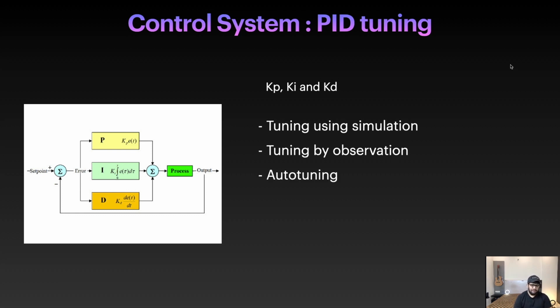One thing that was also very common a couple of years back, when new people were coming into this hobby and they were not from a technical background, they did not understand KP, KI and KD and PID tuning. So some firmware has a feature called auto tuning. What auto tuning is, you take off your drone, you bring it to a certain height, and then you switch the auto tune on, and it will do some motion in all the three axes, and based on that motion it will set the values of KP, KI and KD for you.